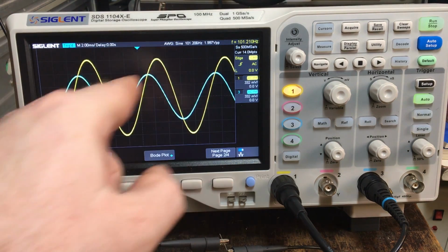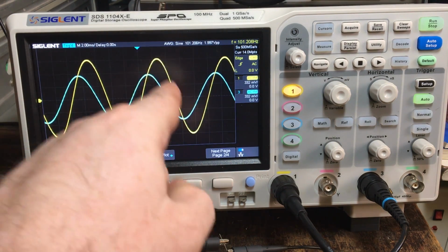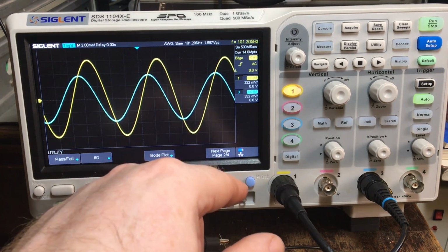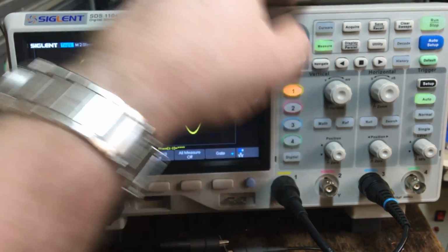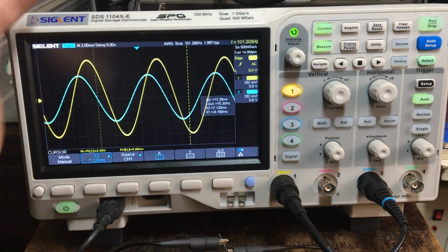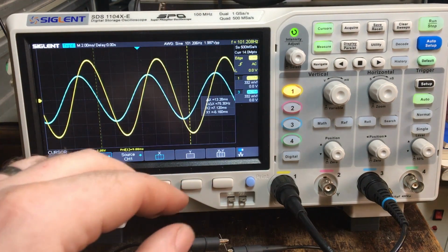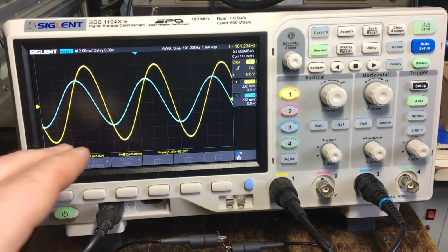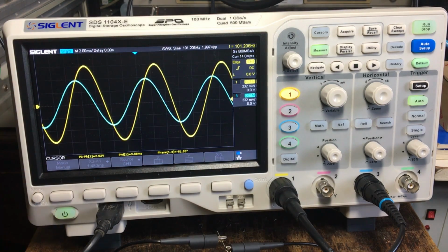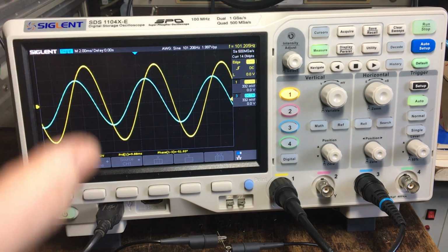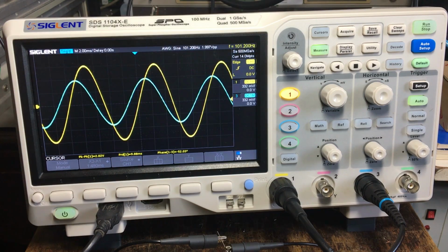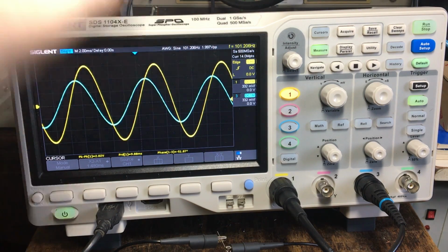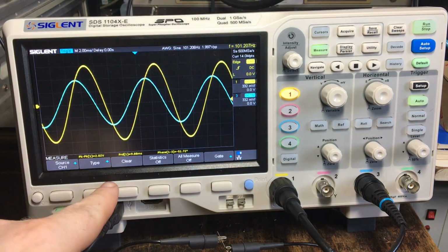And as you can see here from these waveforms, you see the actual phase difference in here. So if you wanted to do a measure on that, you could do it. Yeah, cursors. There we go. I'll come back. So I've got two waveforms here, as I was saying just now. I had to stop because I couldn't find a setting. I had a bit of a mind burp, I suppose. So under measure, you've got the types you can set in here.